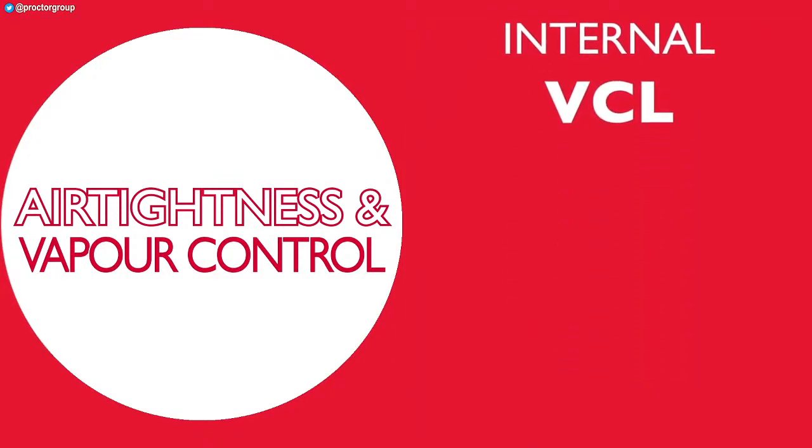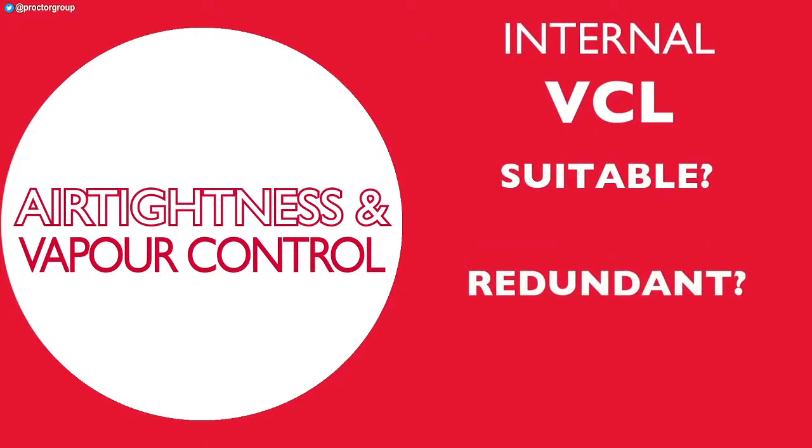It's by no means a given that this method is suitable for all projects, however, and this is particularly true of façade systems. For some façade build-ups, the vapour control function may not even be necessary, and the inclusion of the vapour control layer simply adds an additional process and more complexity for no benefit, just one more thing to go wrong. Which leads to a third consideration.